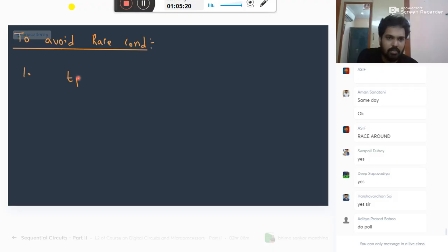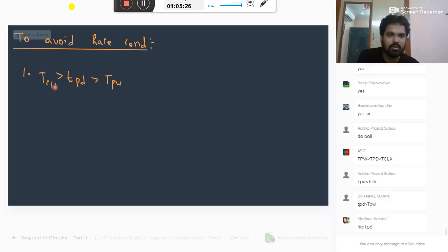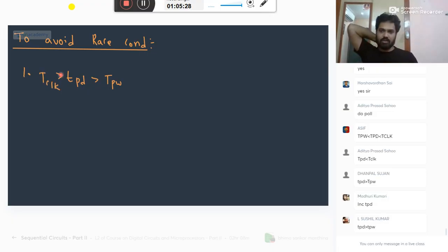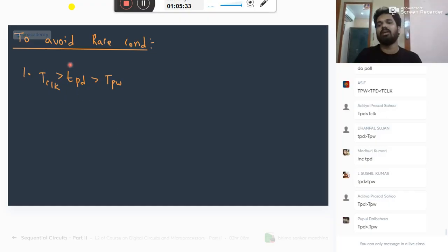Your TPD must be greater than TPW, less than the time period of the clock. But wait, listen here. I should not increase TPD. It is not suggestible. Propagation delay should be as minimum as possible because we have very less patience. We want our systems to be working immediately, not lately.